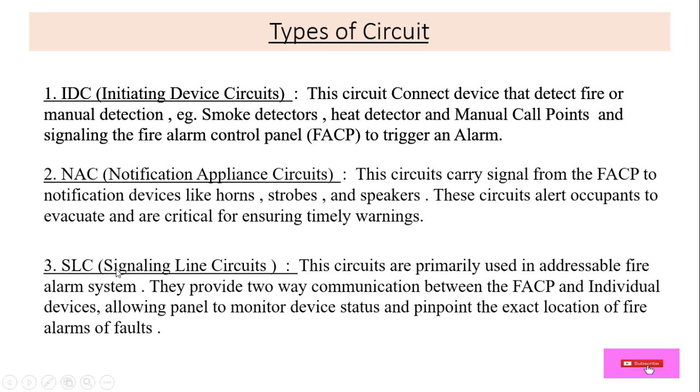Another is SLC, meaning signal line circuit. This circuit is primarily used in addressable fire alarm systems. It provides two-way communication between the FACP, the fire alarm control panel, and an individual device, allowing the panel to monitor the device status and pinpoint the exact location.